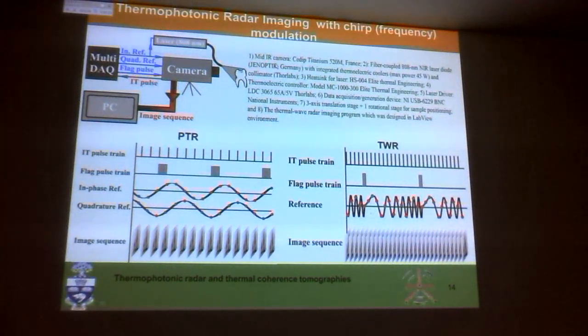Of course, the faster the camera can get, the better the image. But mid-infrared cameras are difficult to modulate, though nowadays maybe 170, 200 hertz. If you can open up at a 200 hertz rate, that means you're sampling. If you sample 4 times, then the highest frequency you're going to get is 40 to 50 hertz. That's what you can get, which is probably okay for thermal fields.